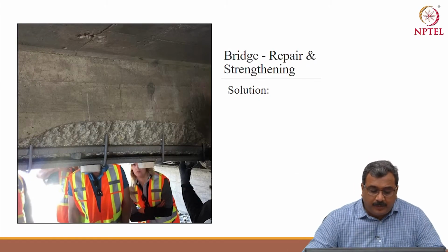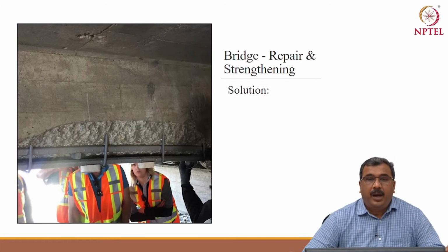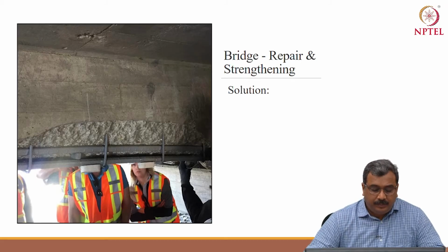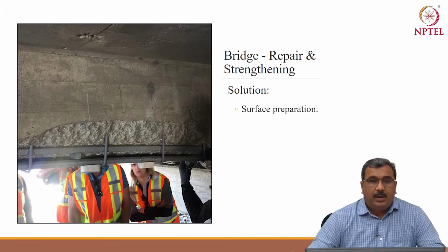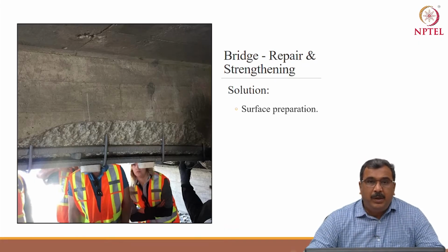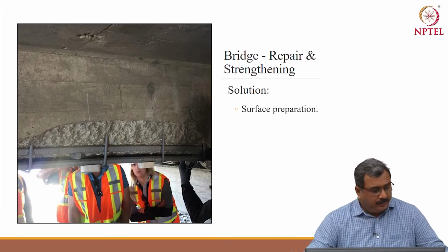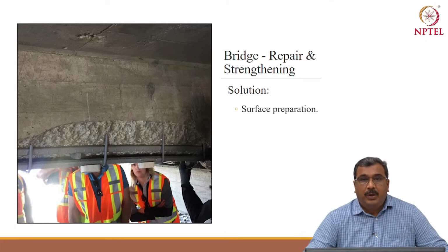So a solution was derived. All the beams needed to be properly prepared by removing all the loose concrete or concrete which is not in good condition.